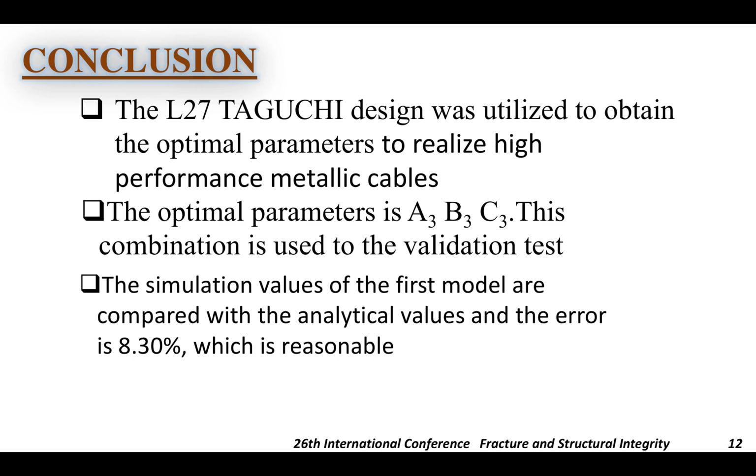The integration of design of experiments, DOE, with the finite element method, FEM, is done to appreciate the effects of parameters such as material type, geometric shape, winding angle, and their interactions on the mechanical behavior of cables. Using a Taguchi experimental design to optimize the parameters, the effects of the optimal condition on the failure stress were studied. We varied 3 factors on 3 levels.